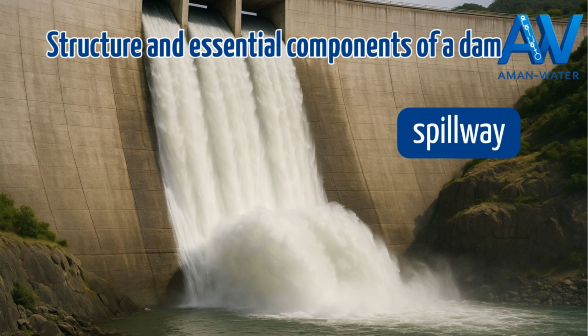Another critical element is the spillway. This is what evacuates floods. When a storm or snowmelt suddenly raises the reservoir level, the spillway allows water to escape without exceeding the dam's capacity. It can be free flow, gated, a weir, or even a labyrinth shape to increase capacity. The safety of a dam often depends on the efficiency of its spillway.